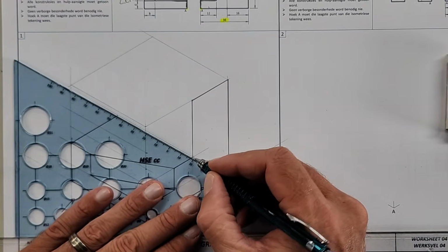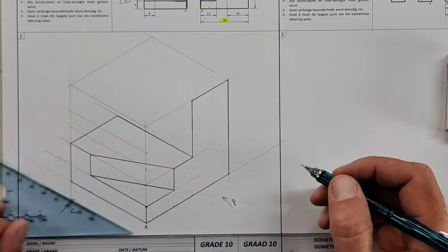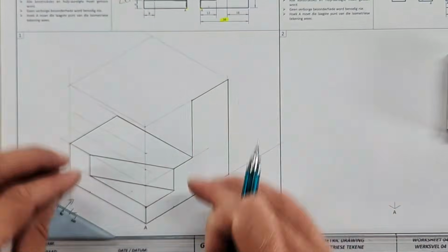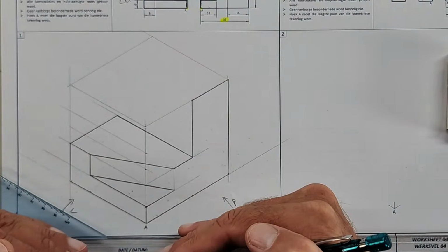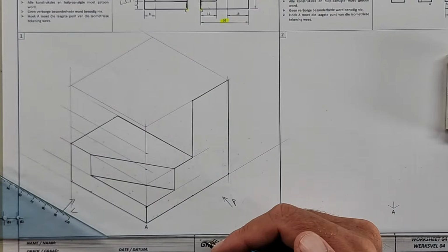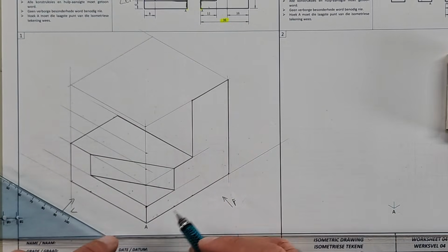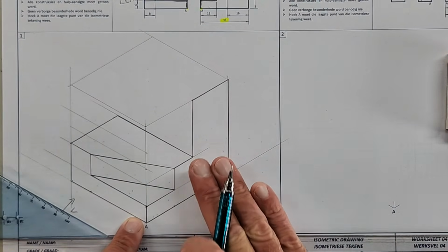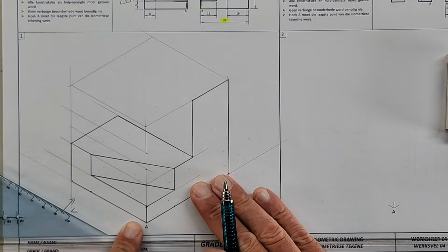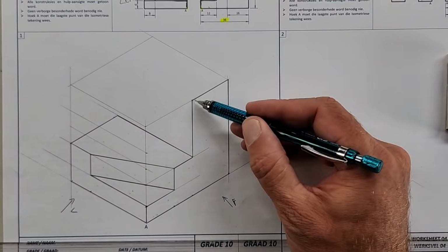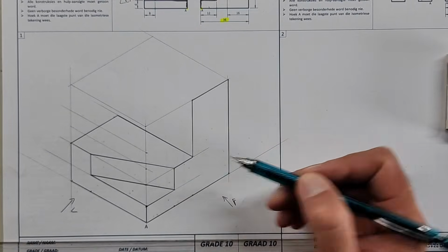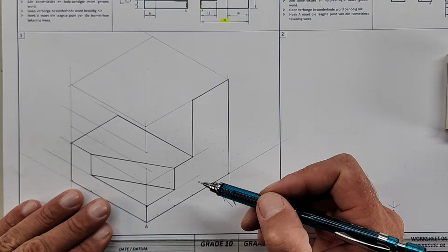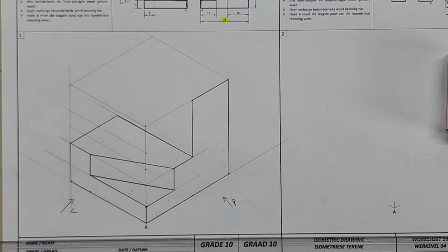So you see what I'm doing is I'm not trying to draw here and then there and then there. I build my drawing from a certain point up. Okay? So I was able to get the front view. If you look at the front view as it is now, we have the outer shape. That's exactly what is given. We've got all the corners that's given. The same with the left view. It's just this top part now that we have to finish.